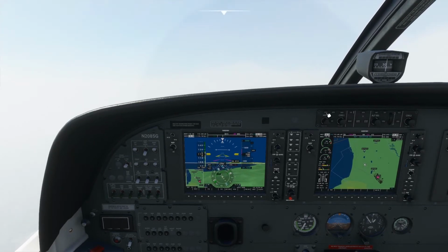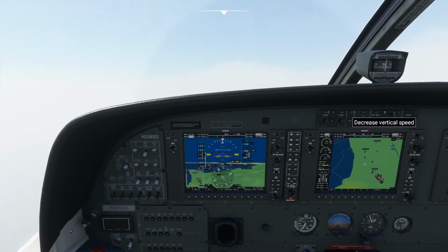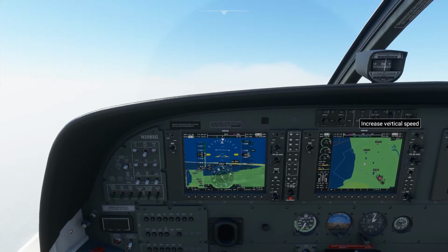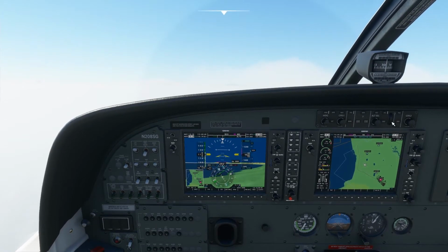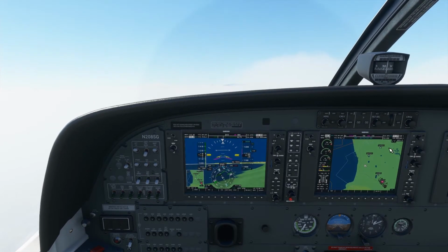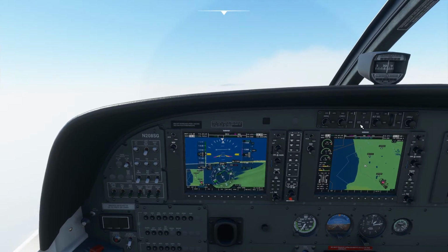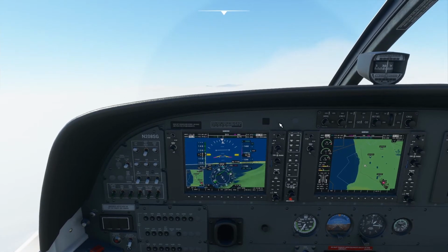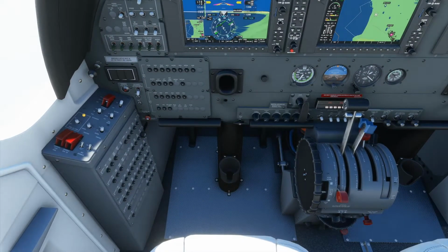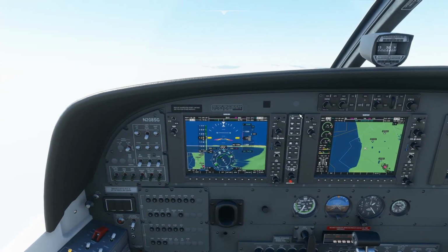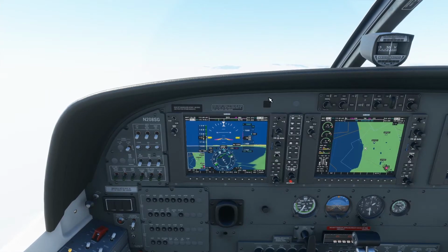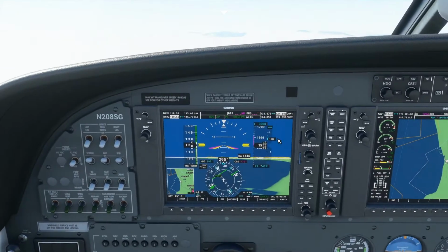Let me turn on the flight director, engage heading select, and the vertical speed here, about, what are we doing? Doing about 1,000 feet a minute. Alright, so that is what we have. And now autopilot. Okay. So let's see, the flaps are up. Engine set. Lights off. After takeoff, checklist complete.